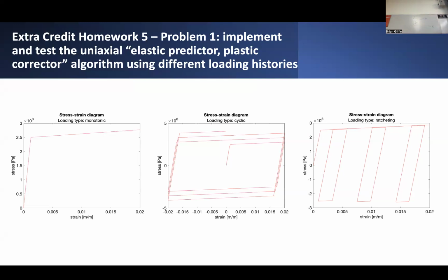And you can see that there are combined effects in this diagram that reflect both kinematic hardening and isotropic hardening. Now, the isotropic hardening component of this diagram is reflected in how the apparent bounds of these cycles of loading appear to be continuously increasing.